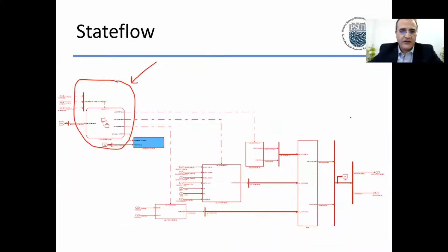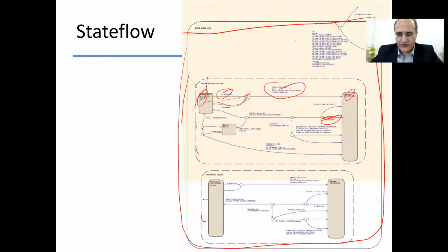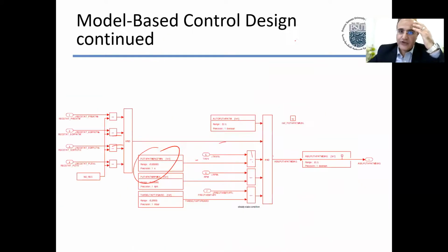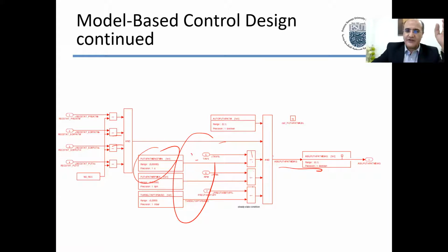Okay, so this block here, double click, is a Stateflow block instead of a block like the ones we just saw. This can bring you to something like this that you can build. Very handy, that makes you think about the functionality, about what to do, rather than thinking about the low-level details of how you're going to code things. Yet you're still developing requirements. I want this to happen when this and this and this are true. These are functional requirements. You didn't write them in pseudocode, you didn't write code, and instead of writing them in a flowchart, you write them in a way like this.